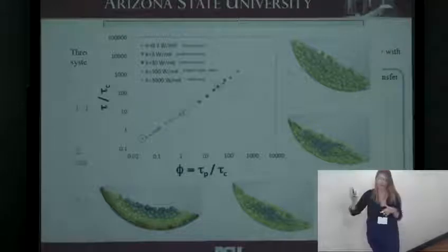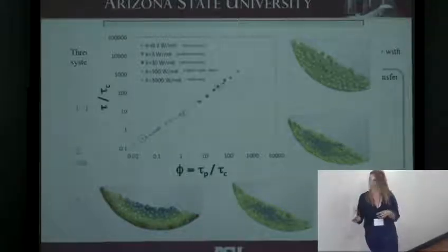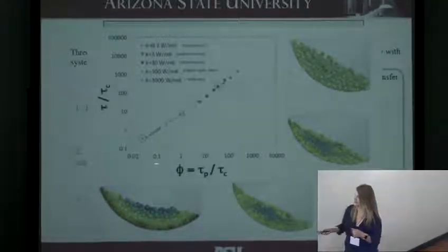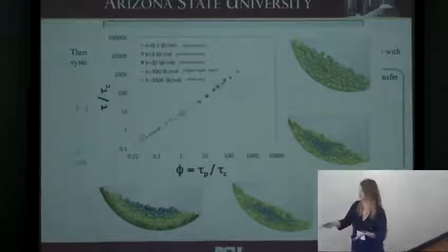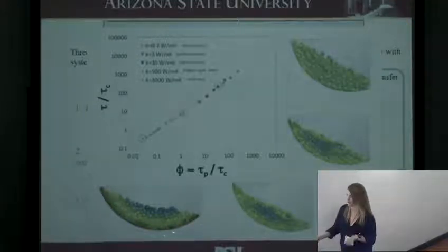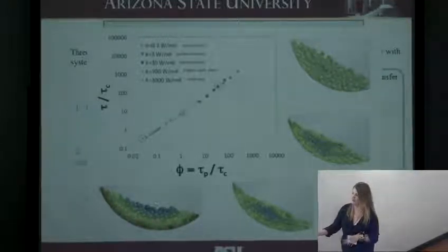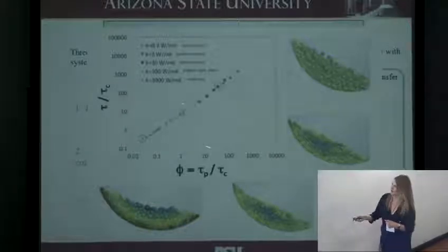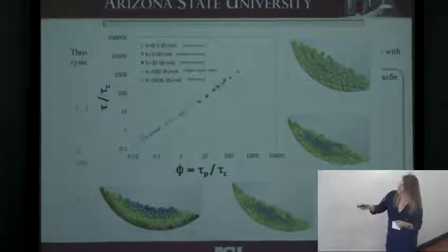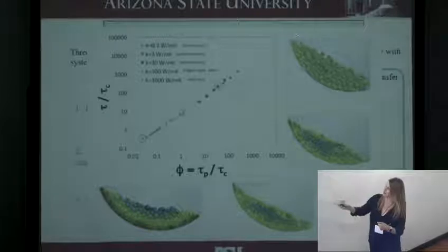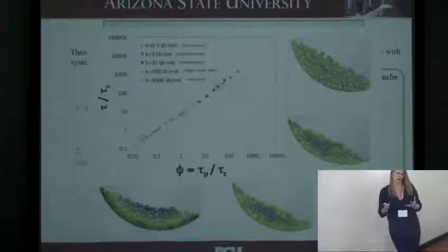And what we found is that there are different heating regimes. At this lower regime here, the particle bed basically heats up like a solid body, where you have a temperature gradient, hot at the wall and then cool towards the middle. In this intermediate regime, we have the particles heating along the outer layer and a cool inner core. And then up at this higher region, we have the particles being very well mixed.